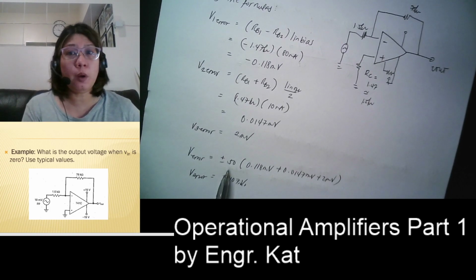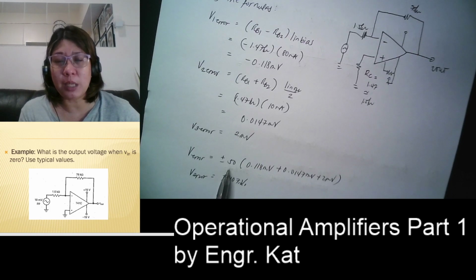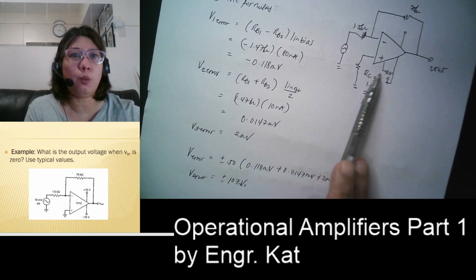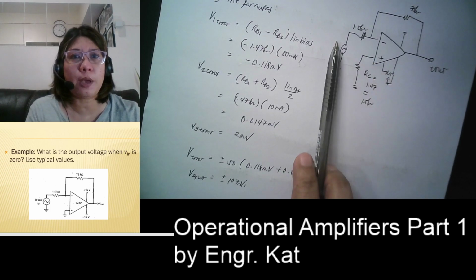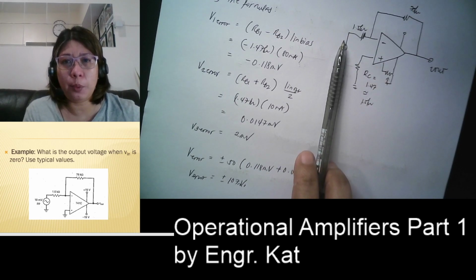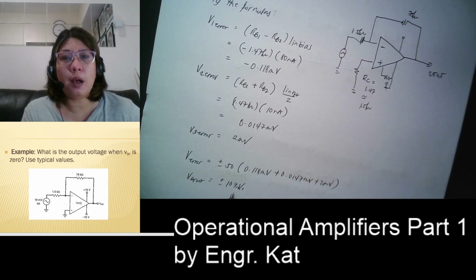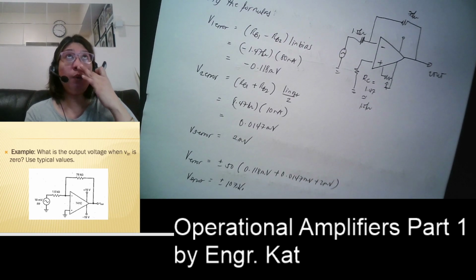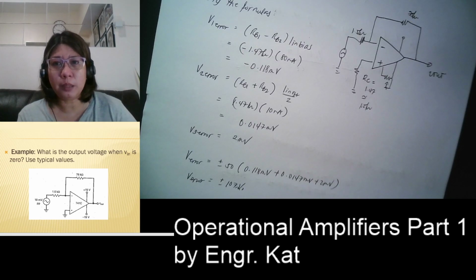Because instead of multiplying this by 100,000 for an open loop voltage gain, we will just make use of the closed loop voltage gain, which is roughly equivalent to 50, which is 75 divided by 1.5. Okay, giving us an error equivalent to plus or minus 107 millivolts. Okay, so what do we mean by compensating resistance?